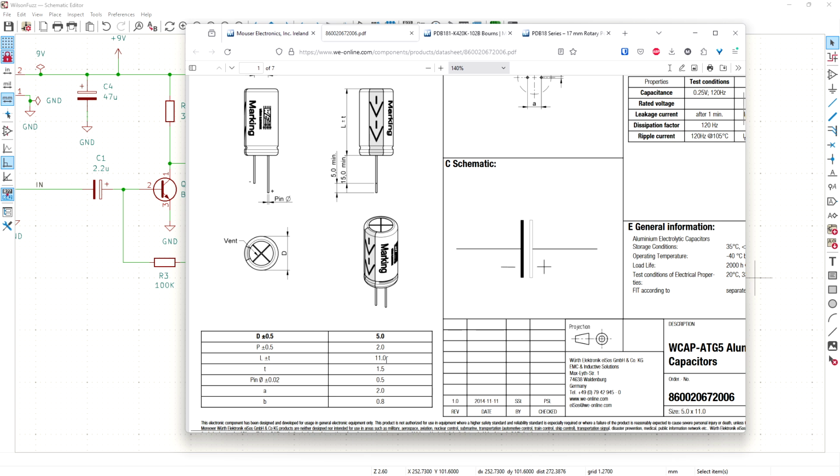This is very important though, because if you're fitting potentiometers with retaining pins, the 9 millimeter ones, you won't be able to fit this on top of the board and screw that onto the enclosure, because this one is going to press against the top of the board. So you might have to fit this underneath the board. Just one of the things, so you see here L is 11.